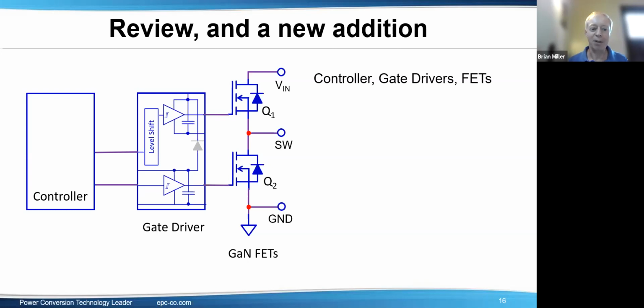Now, a lot of people say, okay, you don't need it for that, but how about for efficiency? You have 2.5 volts on the built-in diode inside the GaN FET, right? And if you have that 2.5 volt drop, then you're going to increase the losses during the dead time, so a parallel diode would help overall efficiency. But in many cases, that's not true, for a few reasons. One is that the dead time is so short, it can just be a fixed value, say from 5 to 15 nanoseconds. So yes, 2.5 volts reverse sounds like a lot, and it is, but for only 5 to 15 nanoseconds per pulse, it isn't that much.